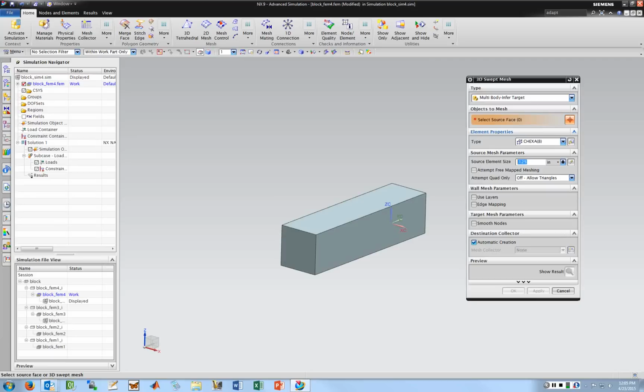This is really important if you're doing CFD analysis, which we can't do CFD in this, but you're going to use swept meshes for any kind of CFD if you can. I mean, sometimes you can't. You have to use a TET, but especially for things like analyzing turbine blades, you're always going to use a swept mesh, and you have to use your boundary elements as necessary. But you don't have to worry about that kind of stuff for a thermal analysis, but I am going to use a swept mesh just to show you how to do it.